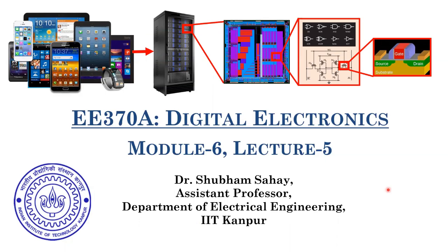So far we have discussed different ways of realizing flip-flops, latches, and registers. One of the most promising ways was that bistable element that we discussed, and even the SR latch uses a similar principle, right? All these mux-based or transmission gate-based designs are basically developed upon that bistable element itself. That bistable element comes in the class of circuits known as multivibrator circuits.